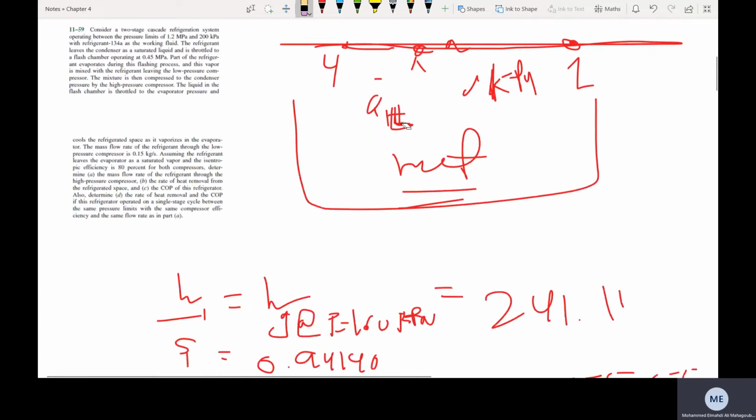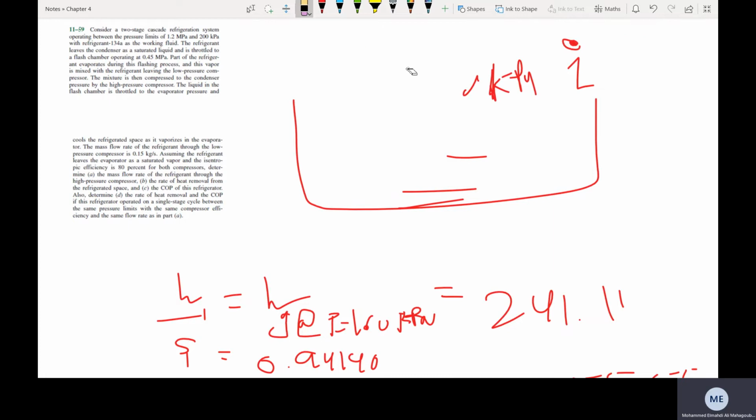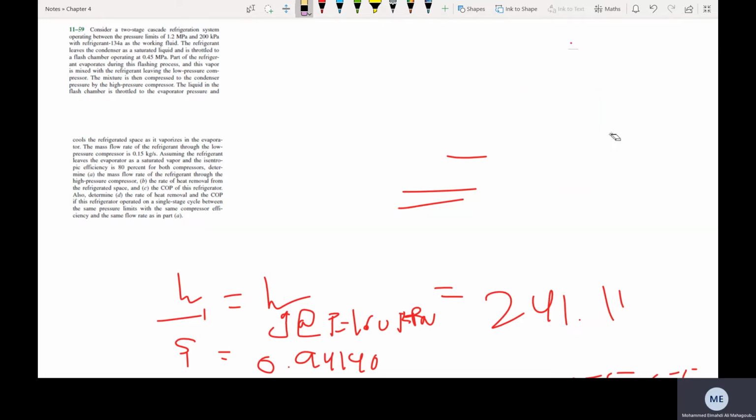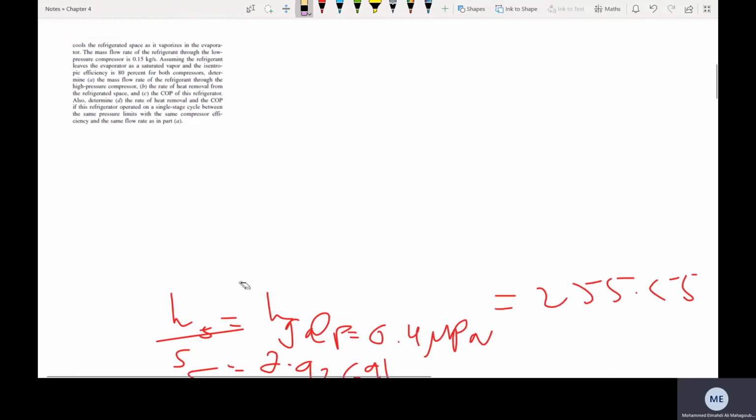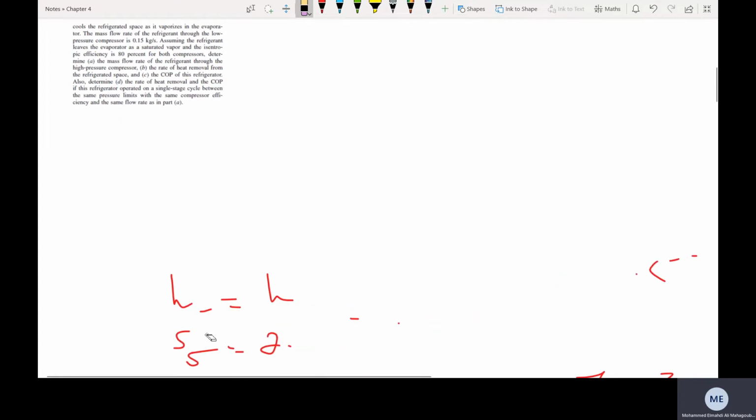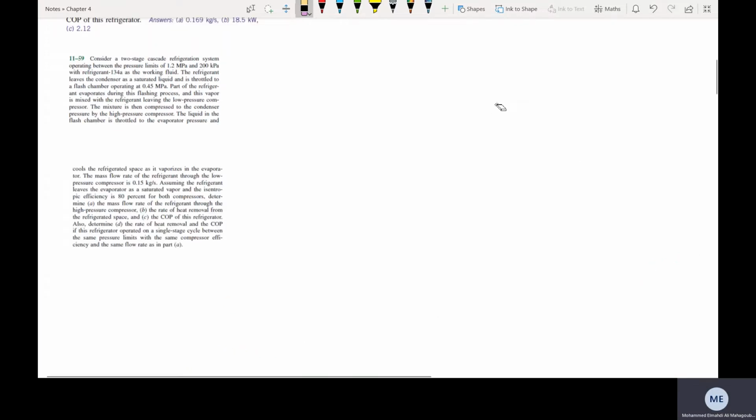and some of the flow rate exiting the throttling device will go to this flash chamber, and a pass from that flash chamber goes directly to the upper compressor, and the rest is going to recirculate through the lower part of the cycle. What do I mean exactly? Let me show it to you in a rough sketch.